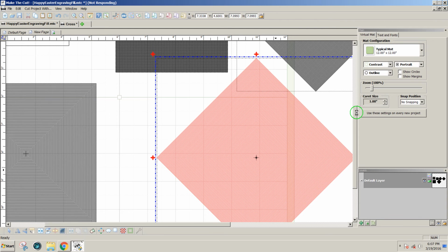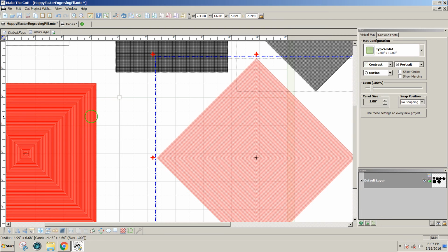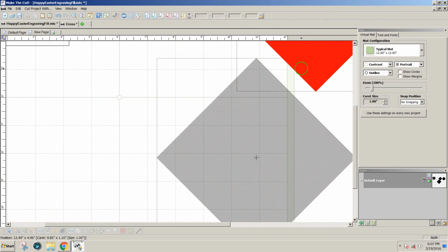It really helps to have your undos limited. I have mine limited to 50 undos. That releases extra memory for processing. You go to Help and Advanced in order to set your number of undos. The other thing is to make sure you don't have things running in the background, like your virus scanner or your backups, that are taking a lot of system resources. The other thing you can do is get rid of a lot of things that you don't need.